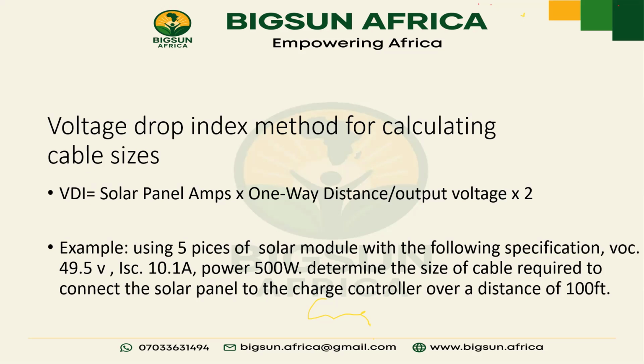Earlier I mentioned that your cable sizing or your connection type is going to be dependent on your charge controller or your hybrid inverter. When we had the 5 panels in series, we needed 4 mm. Now we want to connect these 5 panels in parallel, so we'll see if we still need the same cable.